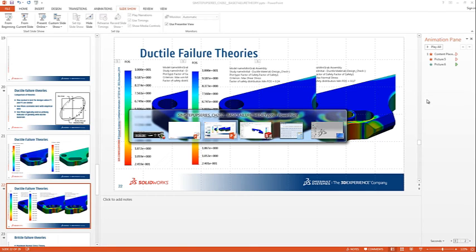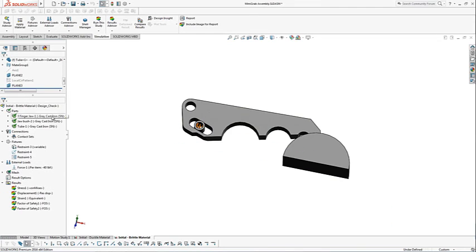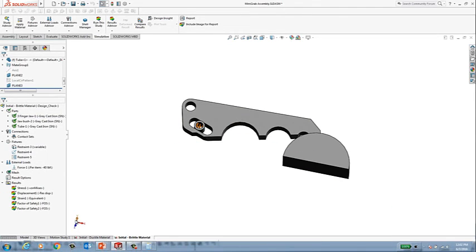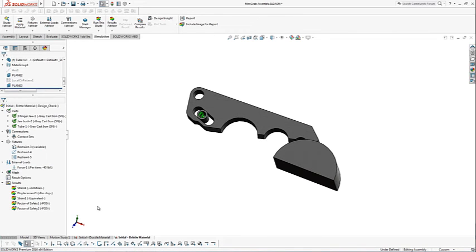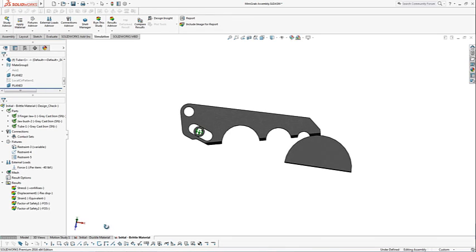And let me just pop back into SOLIDWORKS, and I have another model set up here. So a second study. All I've done is switch the material properties to gray cast iron, which is a brittle material, behaves brittlely. I'm not going to walk through looking at the stress results again, but if we come here to factor of safety, I want to point out a couple things.